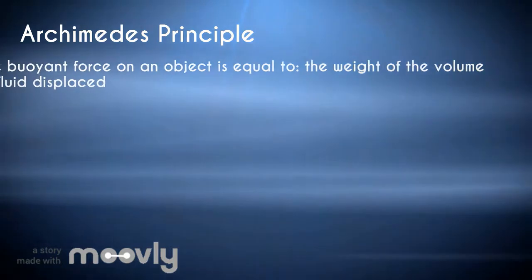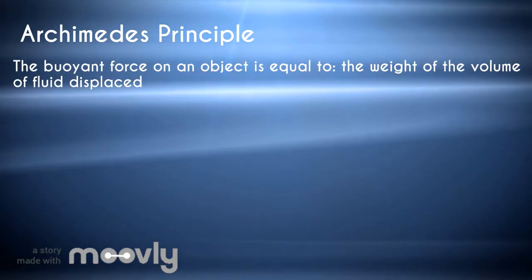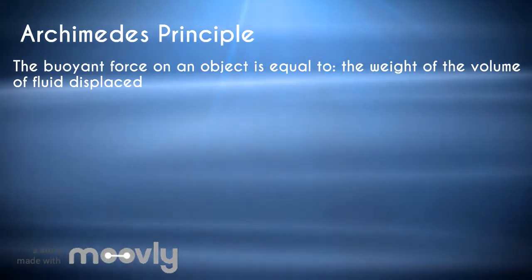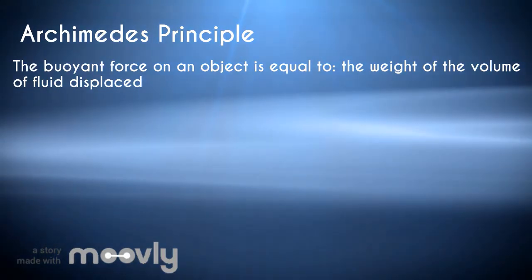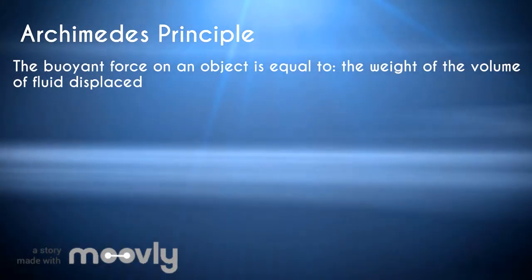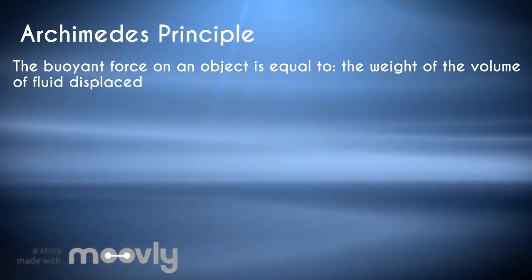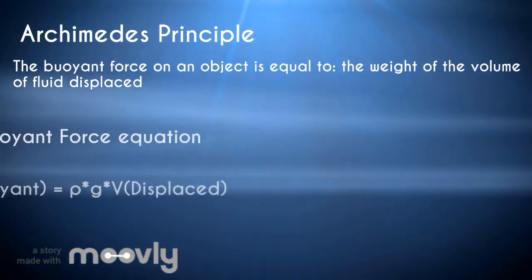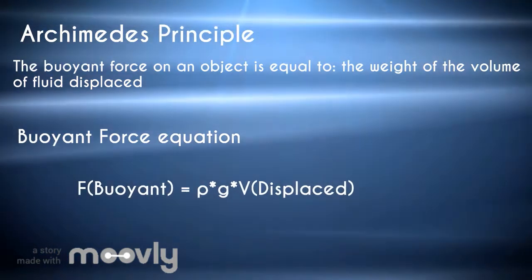The guiding equation for this problem is Archimedes' principle. Archimedes' principle states that the buoyant force on an object is equal to the weight of the volume of the fluid displaced by the object. We also need to keep in mind that the net force on the object will be equal to the buoyant force minus the ballast weight. For a neutrally buoyant object, this should equal 0.